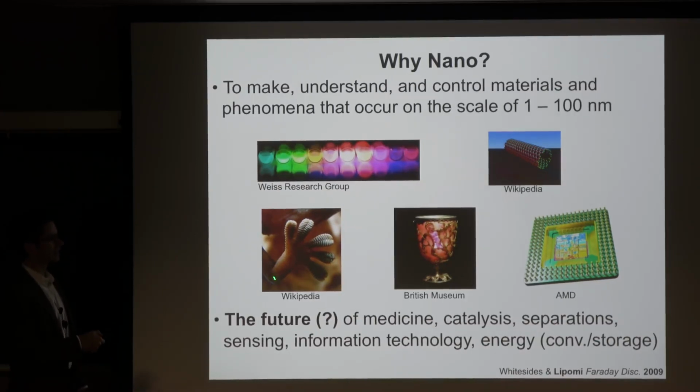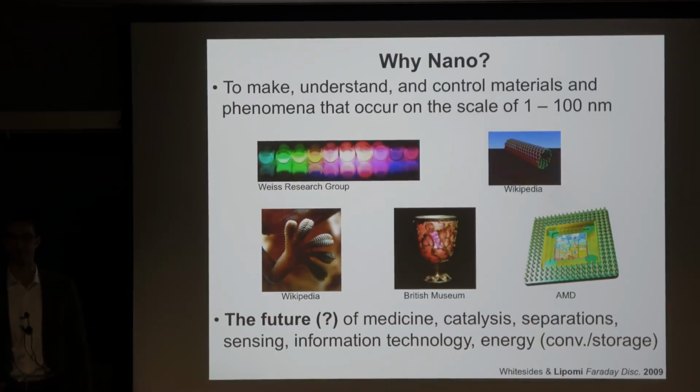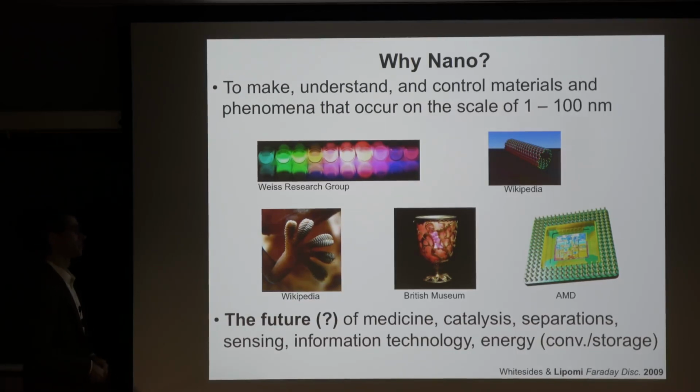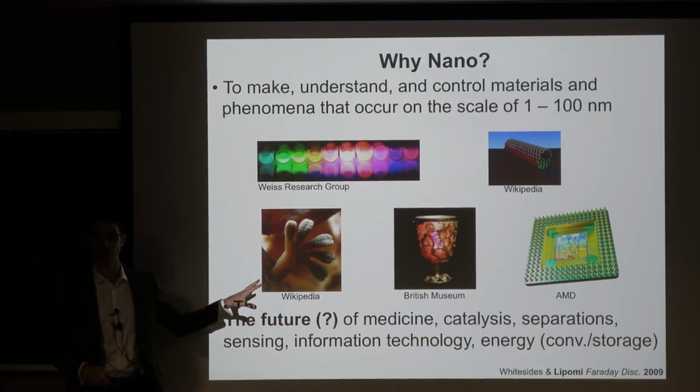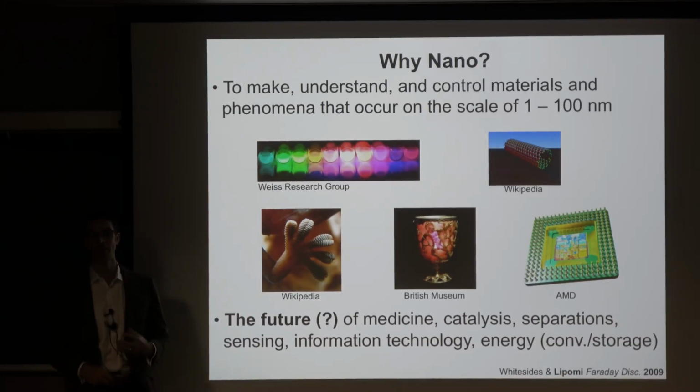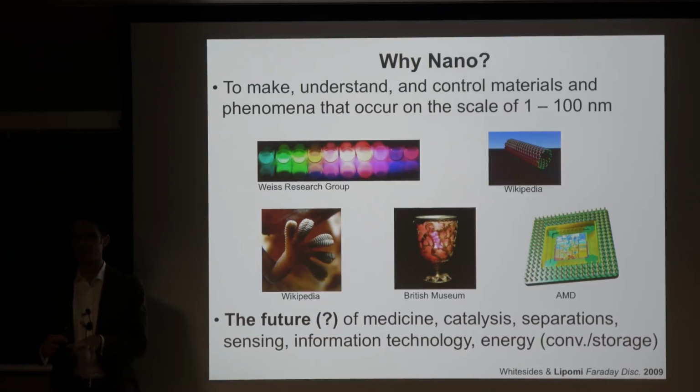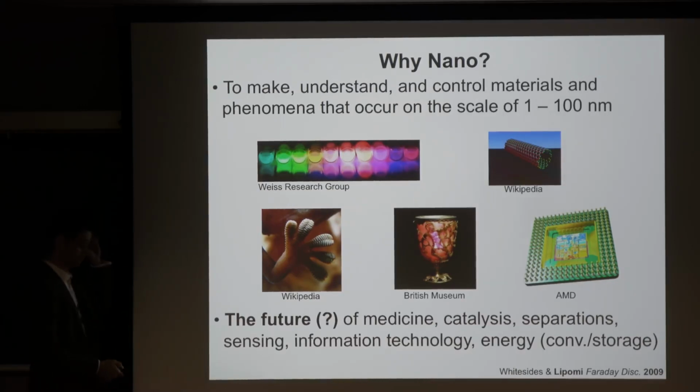This is a gecko foot, which of course adheres by capillary forces to surfaces. No, it's primarily due to van der Waals forces, and while there is a dependence on relative humidity, it's principally because you change the mechanical properties of the keratin of which the gecko foot setae and spatulae are actually made.